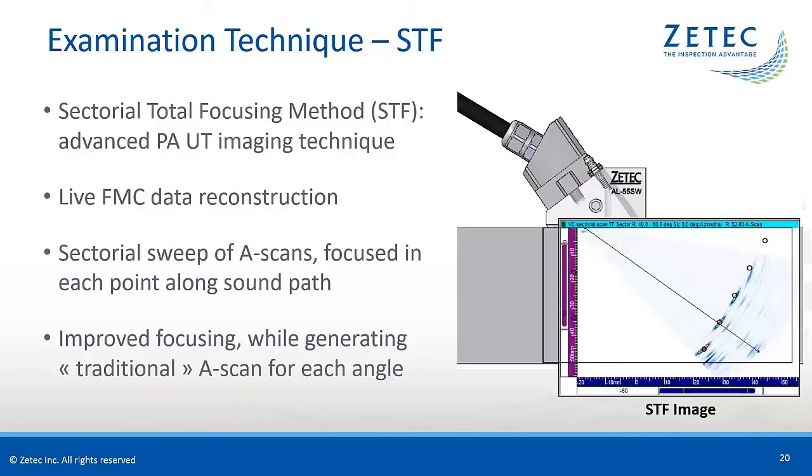Its physical principle is very similar to the well-known DDF, or dynamic depth focusing, algorithm, but this time applied both in transmission and in reception. Again, the operator can perform online data interpretation, or the images can be recorded during an encoded inspection sequence. The algorithm has the benefit of recording a summed A-scan signal for each angle, very similar to standard phased array UT, which may be more intuitive for the experienced phased array technician and facilitate the acceptance in codes and standards.